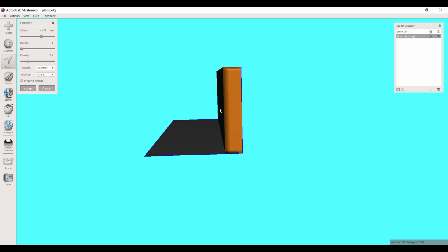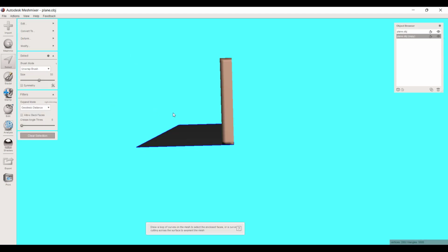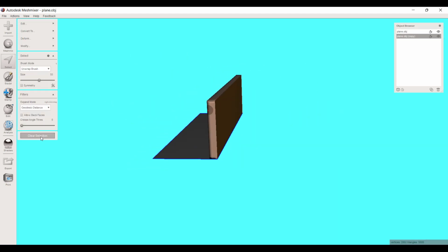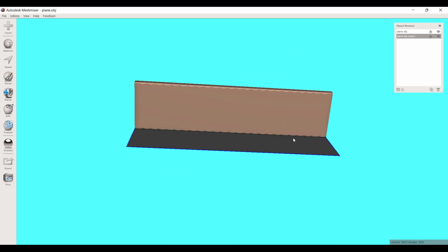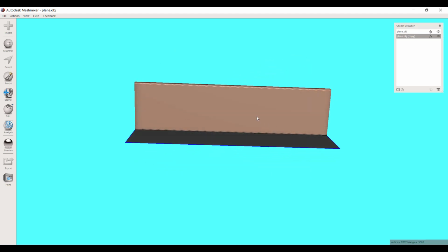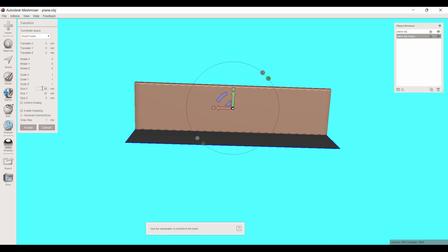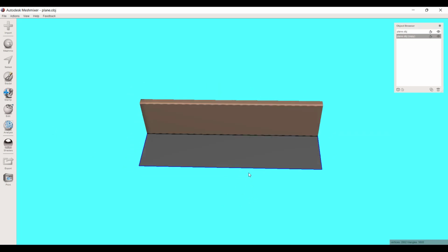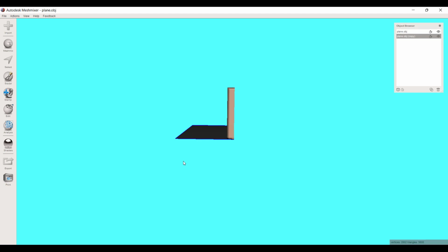Okay, now how far out do I want to extrude it? Well, I can change the offsetting distance of the extrusion to 3 millimeters. All right, and now you see we have a 3 millimeter tank wall. This gives me a reference for how I design the remainder of these parts. If you remember, this was 90 millimeters wide overall, so that's pretty good. We're in the ballpark. Now I need to mock up the bottle.